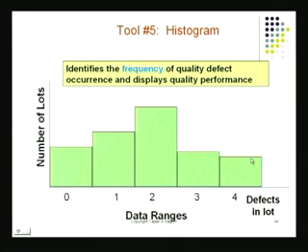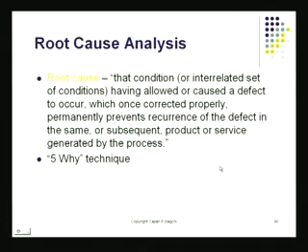Then you've got something called the histogram, which gives you a picture of the history of production. And if on top of this, suppose I'm able to superimpose specification limits, then I can find out what are the parts that are out of specs, and what is the fraction of parts that is within specification. That's something that I could do quite easily with the histogram.